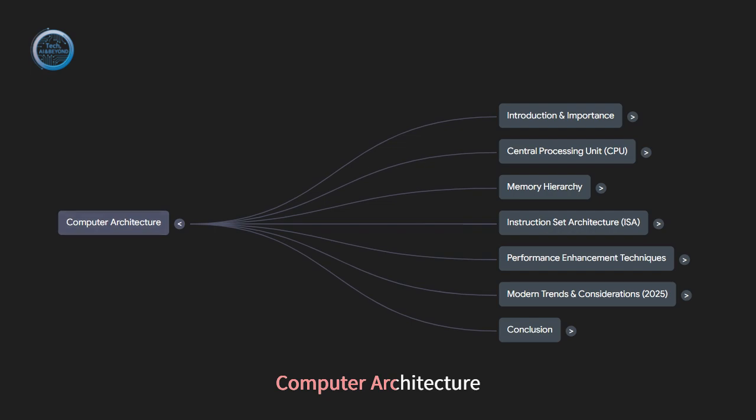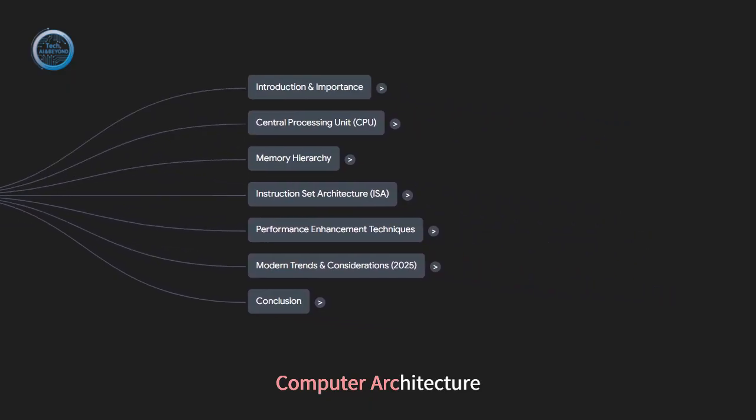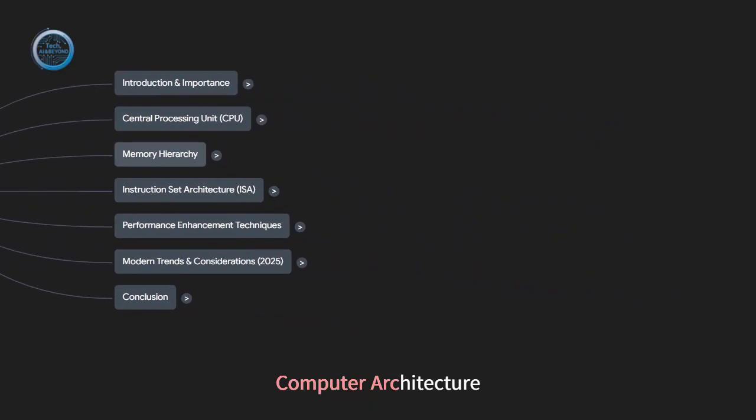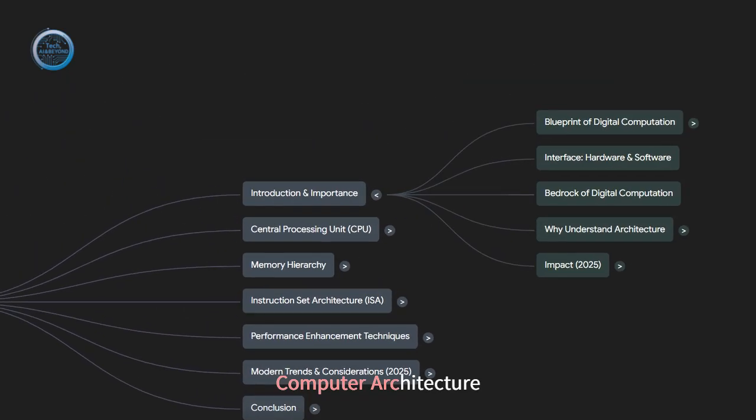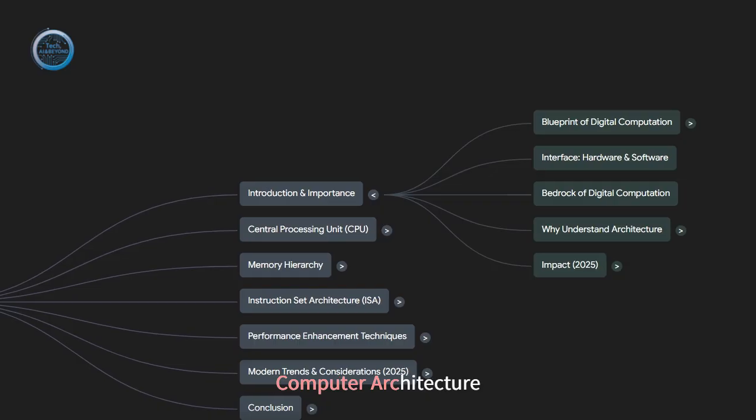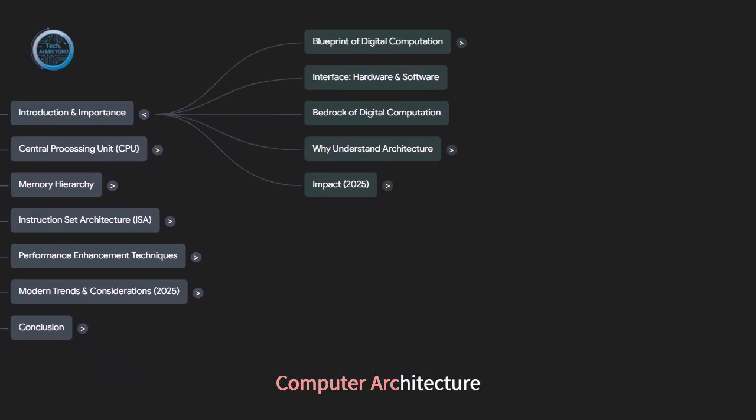It might have to stall, yeah. Pause the pipeline. Or architects use clever tricks like forwarding, where a result is passed directly from one stage back to an earlier stage for the next instruction, bypassing some delay. Another big one is control hazards caused by branches. Branches. Like if statements. Exactly.